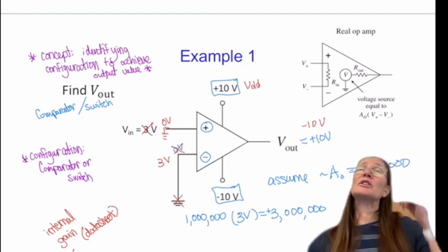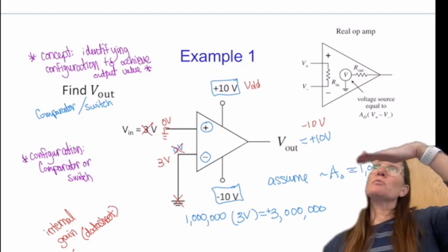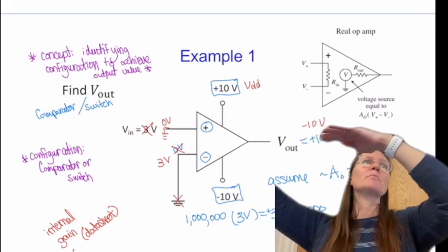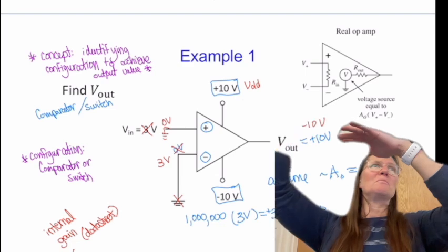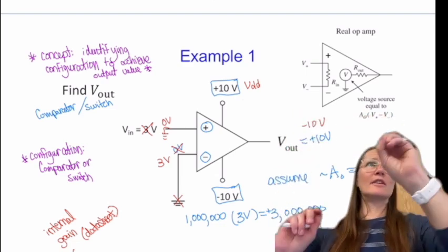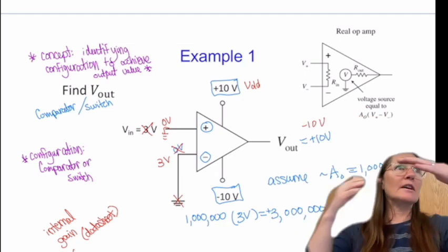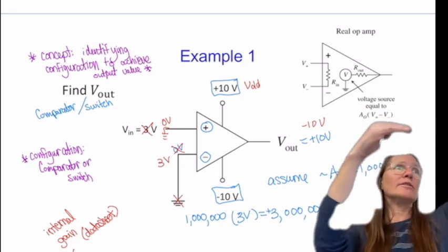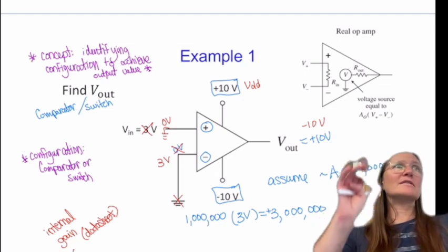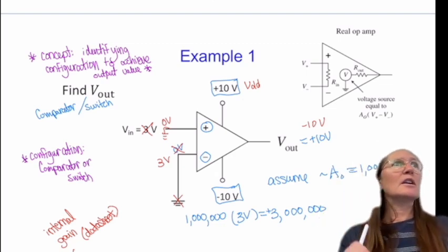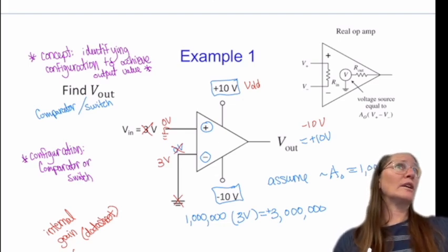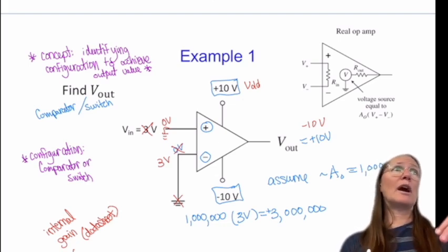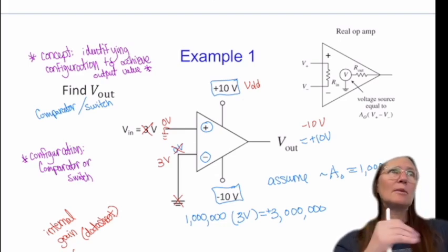Yeah, that's a good question. So with that, if you put 10 volts in there, we can't get higher than 10 volts without having a component in there that actually will boost it. And there are devices that can do that, boost devices, that will move it from a 10 to a minus 10 to a 20 to 0. And so they can shift it like that. But that's a specific component that does that. An op amp doesn't do that. And so it can only go as high of a voltage as you have or as low as a voltage that you have. It can't shift it. Does that make sense?